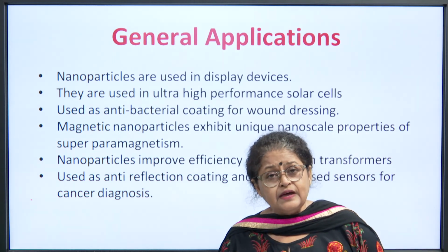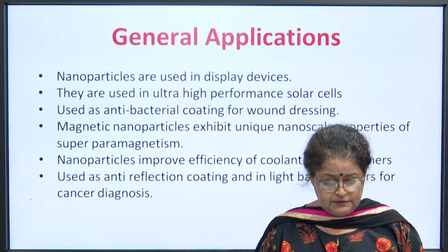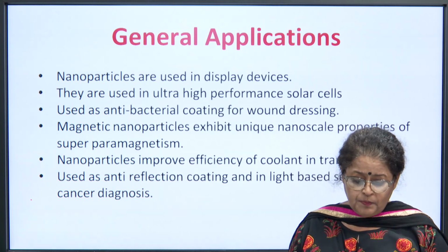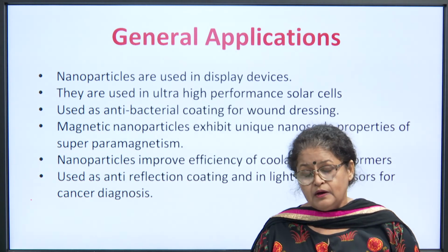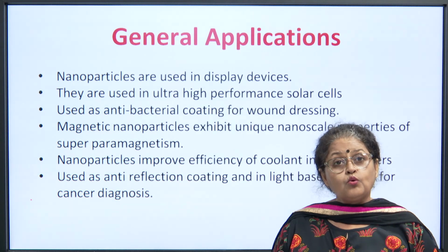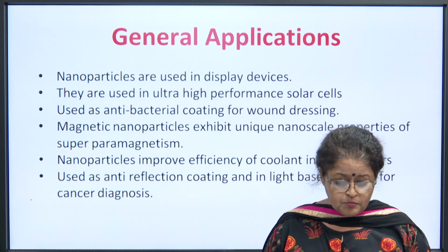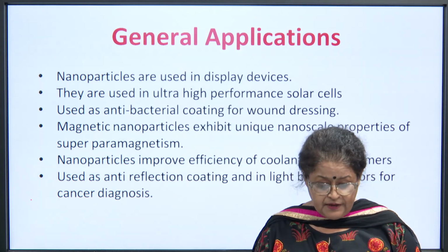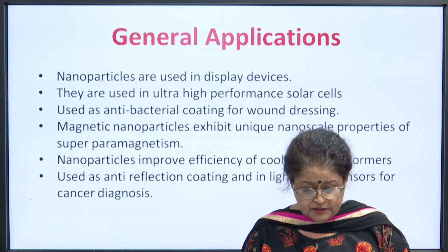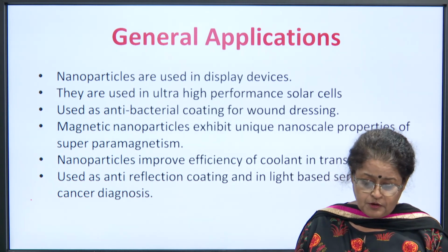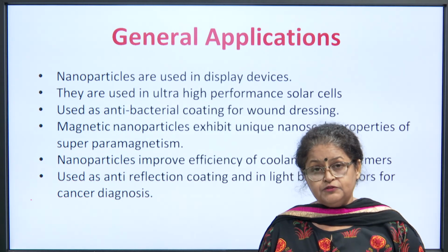So, why do these properties change so tremendously at nanoscale? Because of two reasons. Reason number one, nanoparticle has a large surface to mass ratio compared to its bulk counterpart. And number two, the quantum effect also rules the behavior and properties of a metal at nanoscale, and therefore the properties such as melting point, conductivity, permeability, chemical reactivity, optical properties, magnetic properties change as a function of the particle size.